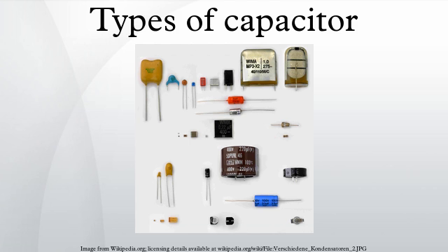The plastic films used as the dielectric for film capacitors are polypropylene, polyester, polyphenylene sulfide, polyethylene naphthalate, and polytetrafluoroethylene, or Teflon. Polypropylene film material with a market share of about 50% and polyester film with about 40% are the most used film materials. The rest, about 10%, is used by all other materials, including PPS and paper with roughly 3% each.